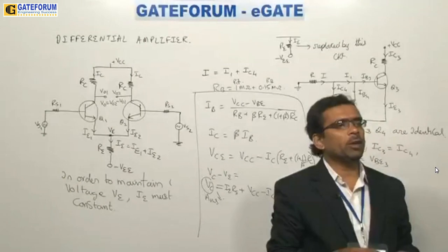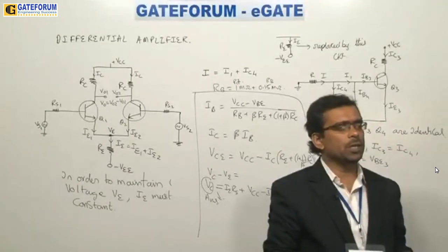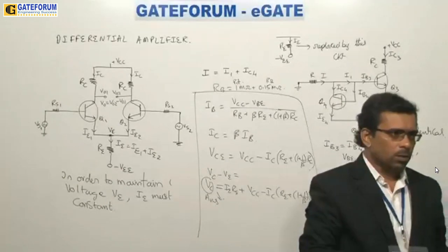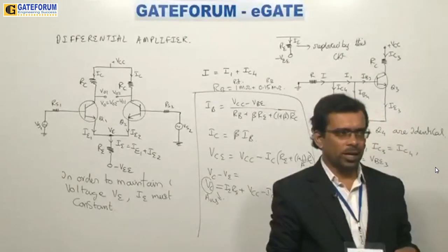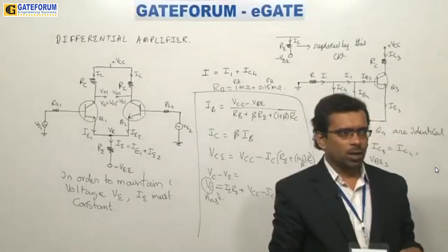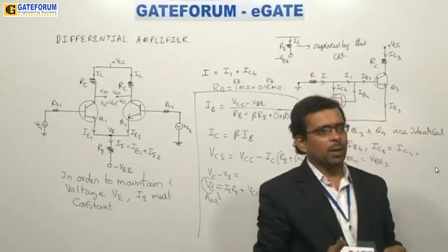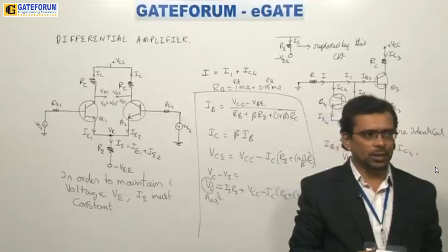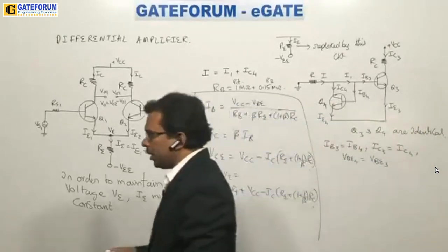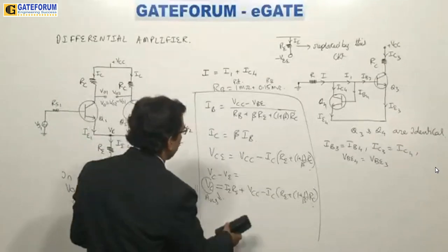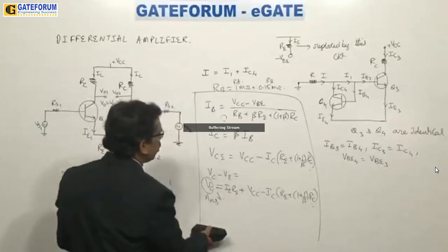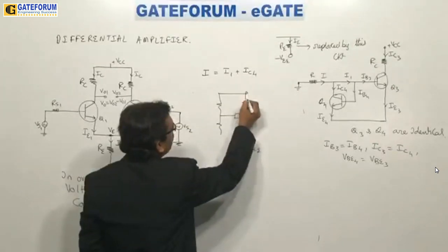Next, Saloni from Ahmedabad. In the voltage divider circuit, R1 R2 equal to 50, VCC is 18 volts, VE is minus 18 volts, RC is 1 K, and RE equal to 7.5 K, beta 130. Determine IB, IC, VCE. Very simple. Only a small difference you get here, that is VE is given in that circuit. Given minus VE. This is the only difference which you have.